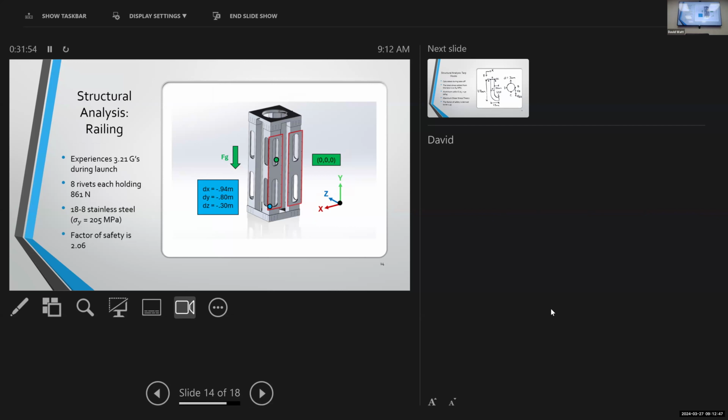But I would expect vibrations to be significant here, so I would look into what the launch vibration environment is. It's going to depend somewhat on where you're located in an ascent vehicle, and on your mass and how you're mounted to other things. But I would definitely take a look at acceleration. Yes, sir. Or at vibration.